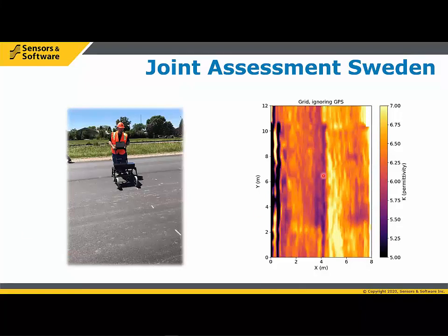Another example here, one of the things that became obvious to us early was that we could see a lot of variability at the joint between lanes, and this shows up very clearly in this example from Sweden, but we have a number of examples like this, and so it's an interesting way of using GPR data. And one of the things we found is it's usually better to do the profiles across the road like this, and then you can see the variability in the joint. When you run parallel, it's harder to stay aligned with the joint, so you get a much fuzzier picture of what's going on at that joint area. Again, optimizing your methodology for a particular application.